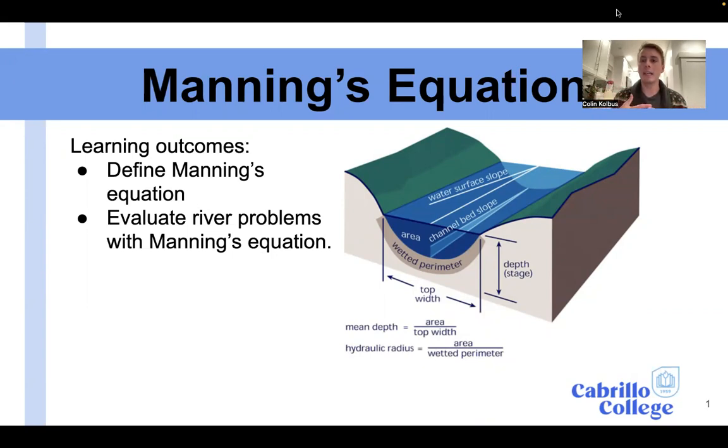It is basically the most general application of our understanding of the conservation of mass to calculate the velocity of a river, based off of the friction of the bed, the properties of the soil, the sediment, the plants growing through it, the slope of the river, and the cross-sectional area through which the creek is flowing.